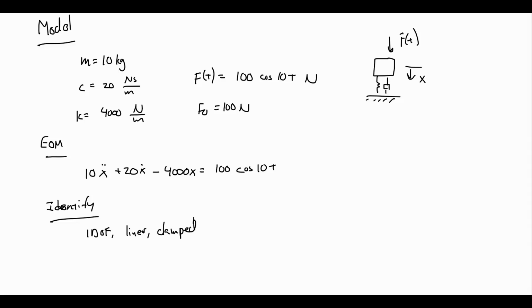Now we will be concerned, is it underdamped, overdamped, critically damped, which we're going to see in a moment. We see the right-hand side is going to be non-zero. We have an explicit dependency on t on the right-hand side in that cosine. So it's forced, but it has a constant amplitude, and it is a simple harmonic. So we have simple harmonic cosine forcing.